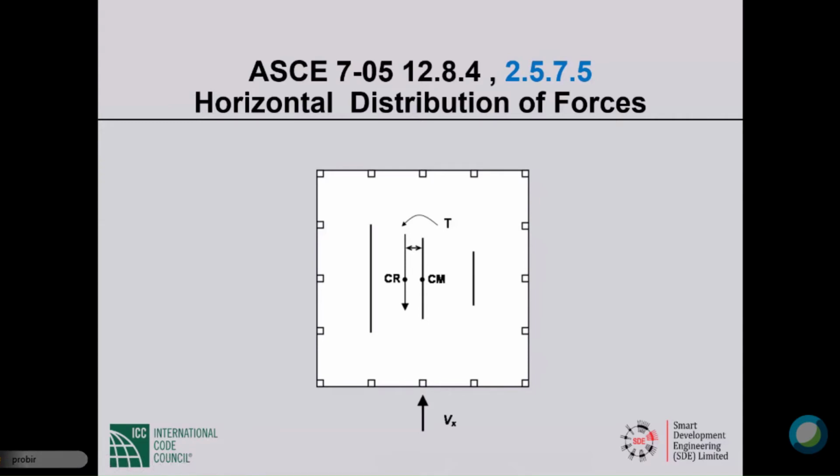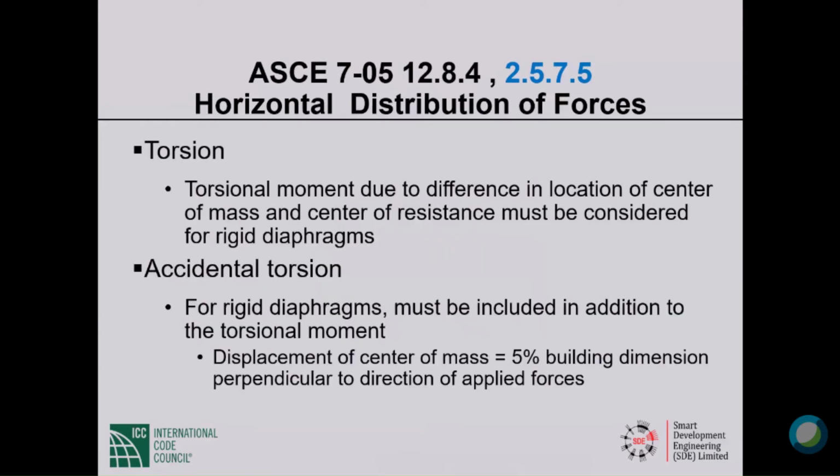But anyway, you get the idea. So that's how torsion comes into the picture. It is not only the story shear, but also the torsion. The torsion will increase the forces in this frame, in that shear wall, and will take away from the forces from those 2 shear walls and the frame. The take away we ignored in design, but the addition we have to consider in design.